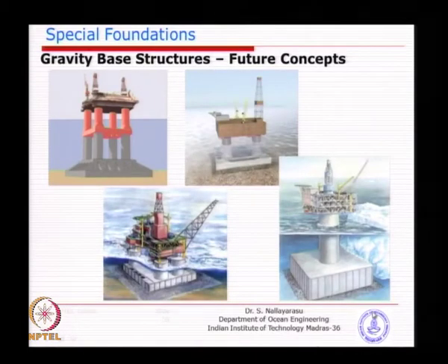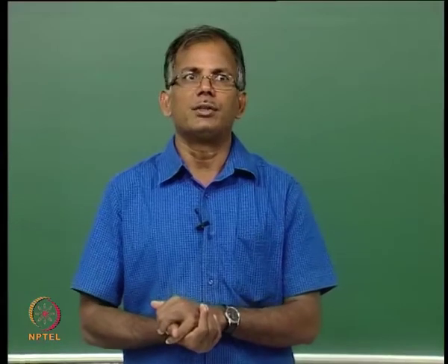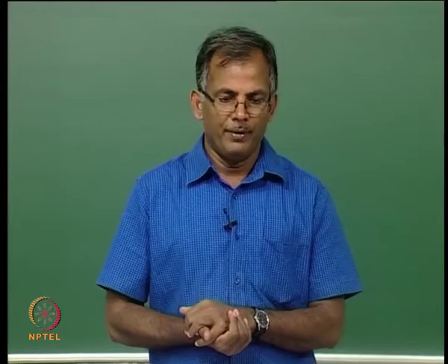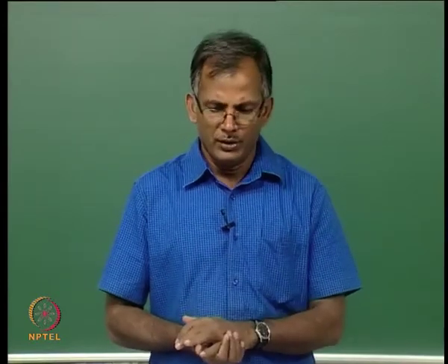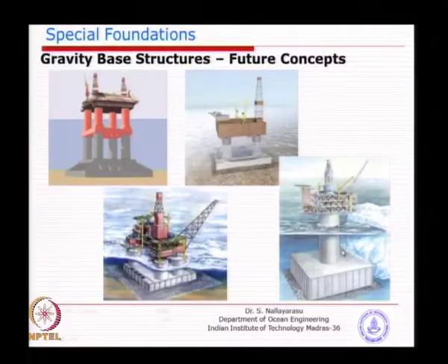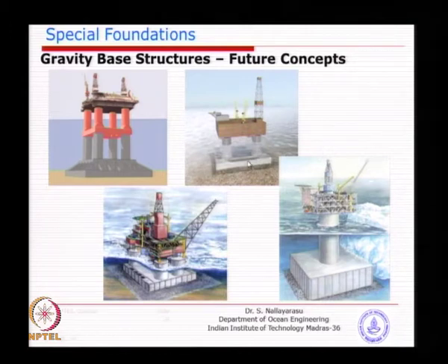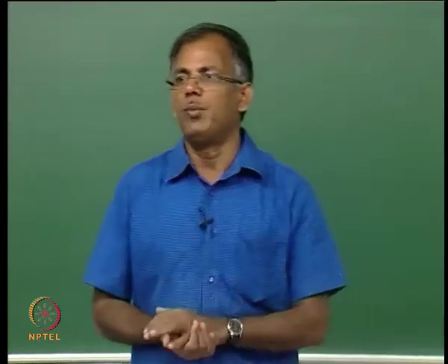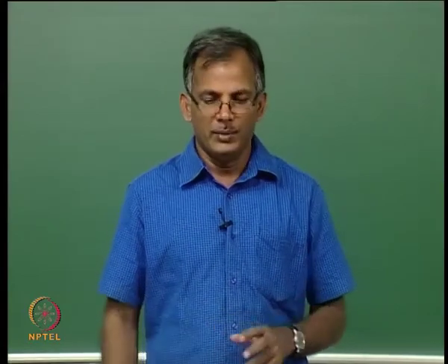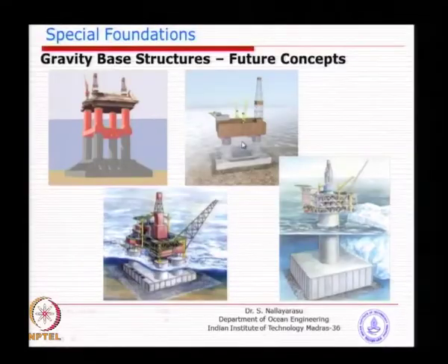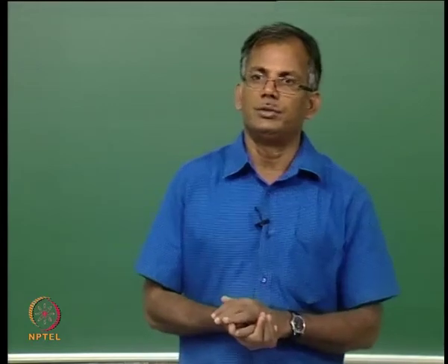Various other forms of this type of gravity structure you can imagine, in terms of what kind of structures are required for making sure that stability can be achieved both in installation and service. You can see here a single large diameter shaft with a bigger base dimension. Here you can see only 2 columns, it is not necessary to have 4, because the area requirement is smaller, so you can have 2. But again the design needs to make sure which orientation is better, because you need stability in this perpendicular direction, because if the sea waves are larger you will get negative pressure at this side, which is not very good.